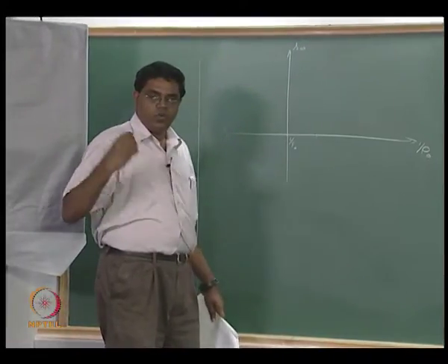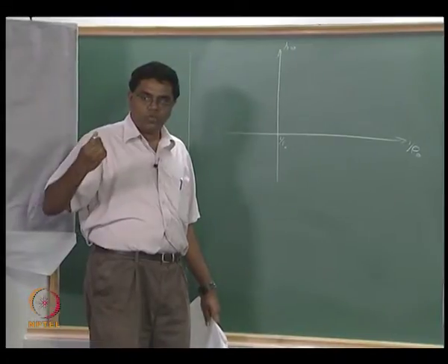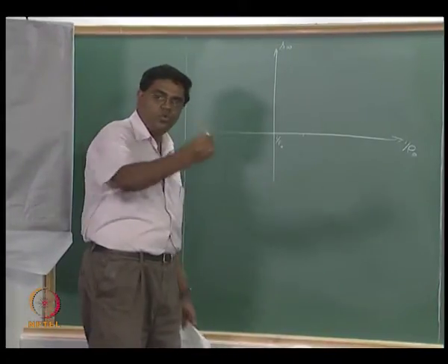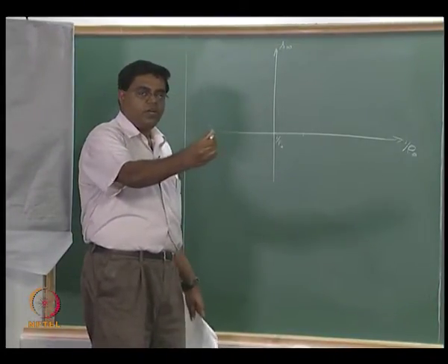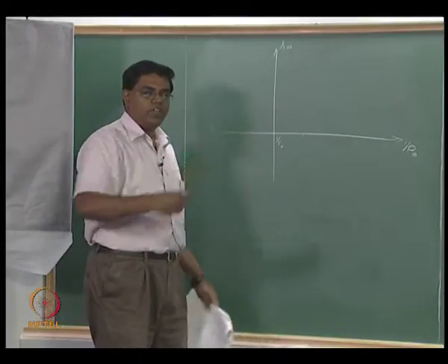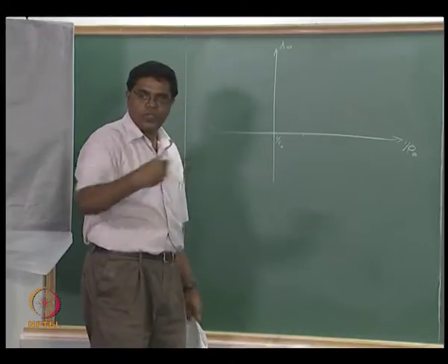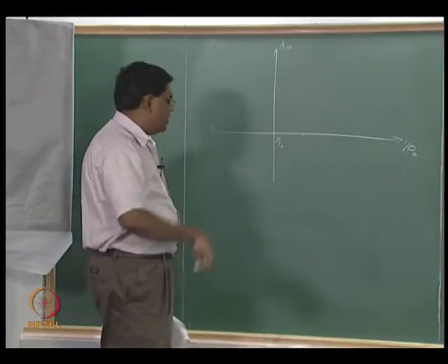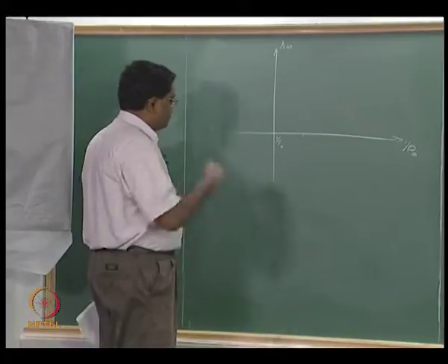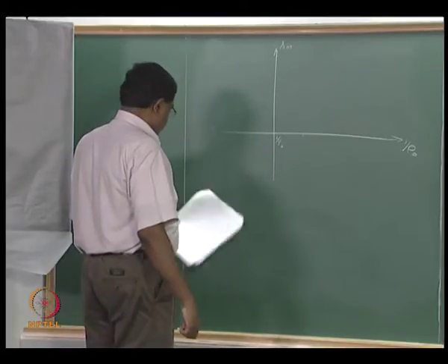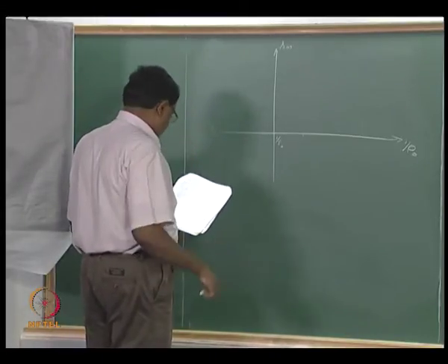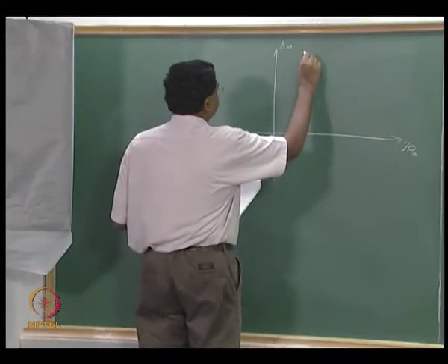That means 1 over rho infinity goes from 1 over rho naught as the initial condition to a value, it jumps to a value where the Hugoniot cuts the x axis passing through the origin, right, because above this you have the first quadrant in the Hugoniot plot which is forbidden, and therefore you will find that you now have